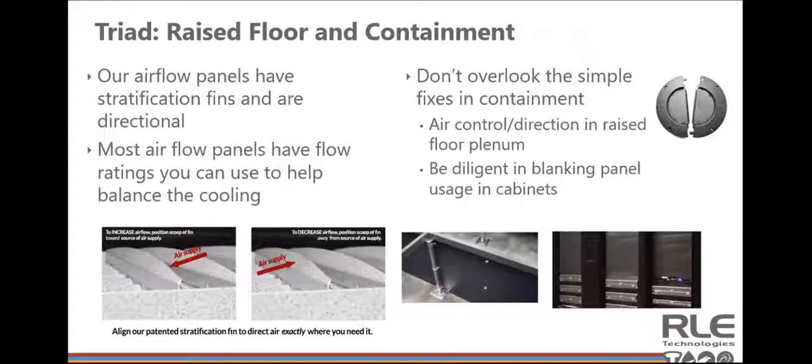Starting off, airflow and airflow tiles are a big thing. A lot of tiles I found are directional other than just straight perforated tiles. So make sure you're paying attention to how those directional tiles are installed. As you can see in the photo here, ours use stratification fins.